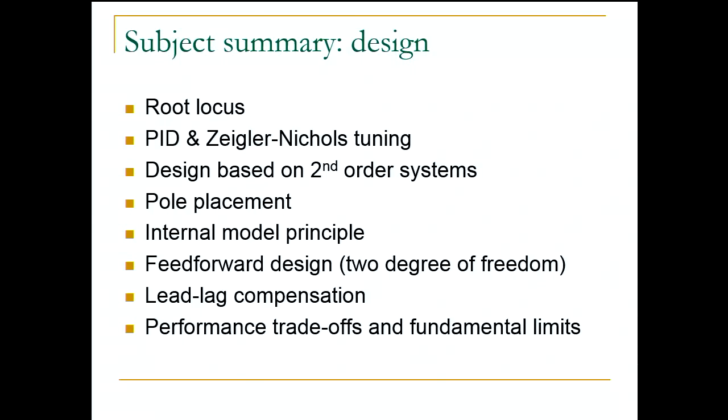We saw how to design internal model principle controllers. They are the controllers that allow you to track a reference, let's say a sinusoidal reference at a particular frequency, or even constant references with zero frequency, or reject certain disturbance inputs at a certain frequency.